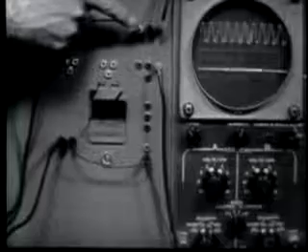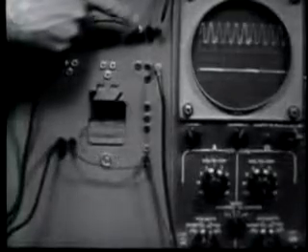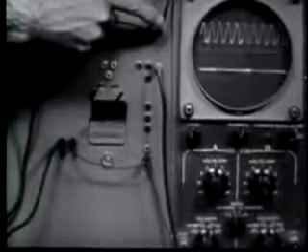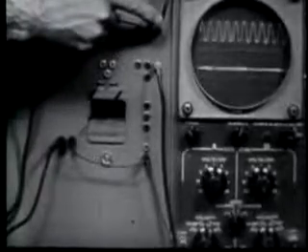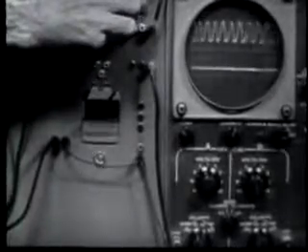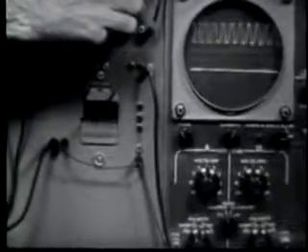Through this direct connection, we can see the input frequency displayed on the A trace or the top trace of the oscilloscope. The other lead here, the one in the middle, is used to provide a synchronization voltage or an external trigger for the sweep circuits of the oscilloscope.